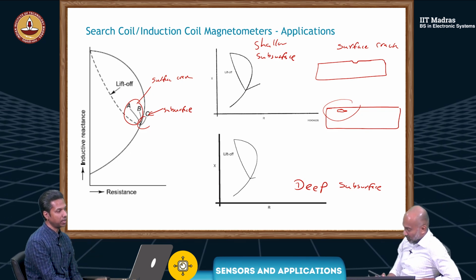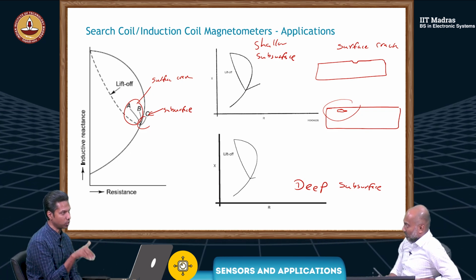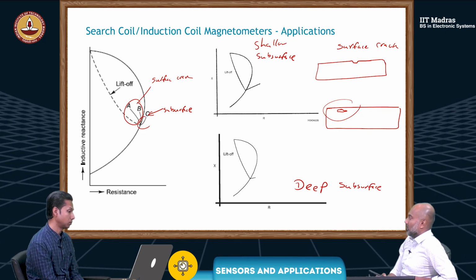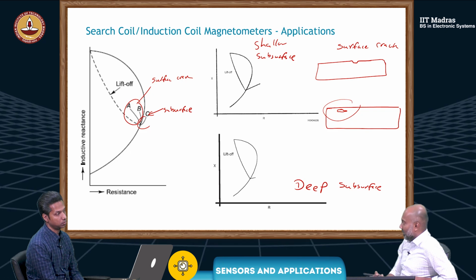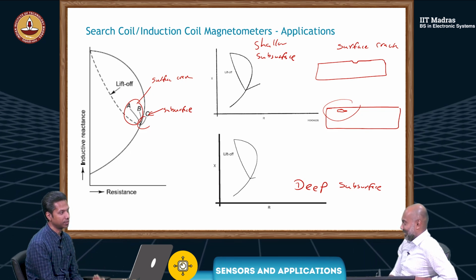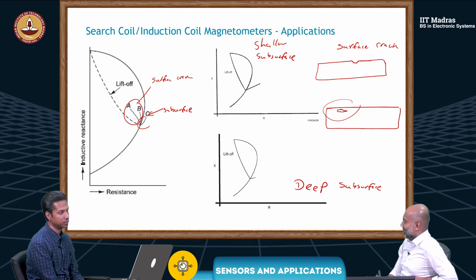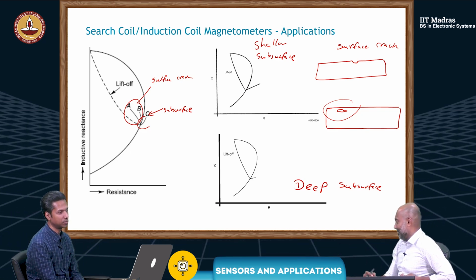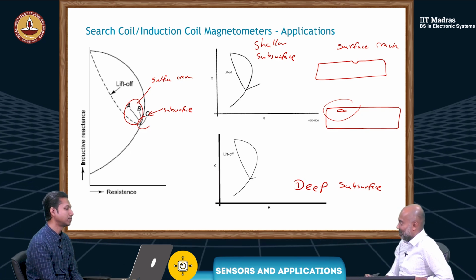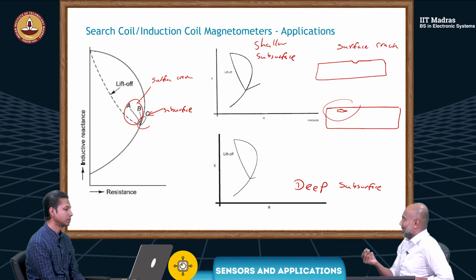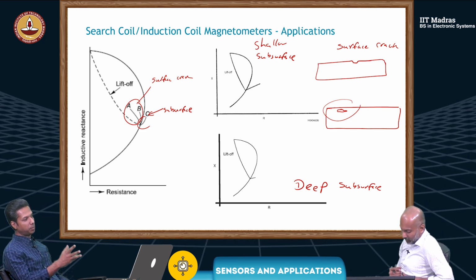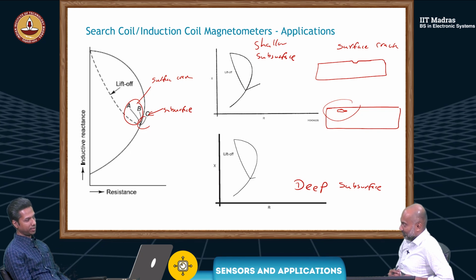So to some extent, we can even say whether it's a surface crack or a subsurface crack. If it's a deep subsurface crack, you cannot see it, but you still can't sell your product, and you will have to send it away, because there's a weakness, a weak point inside. So it makes sense, this non-destructive testing.